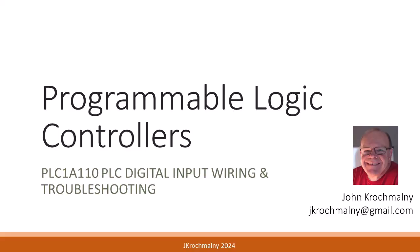Programmable Logic Controllers, or PLCs, are frequently found in many applications involving automation and instrumentation. In this presentation, we will cover the typical digital input wiring associated with the common programmable logic controllers. We will also explore various troubleshooting techniques necessary to determine and correct problems related to digital field devices that are connected to various types of PLC assemblies.